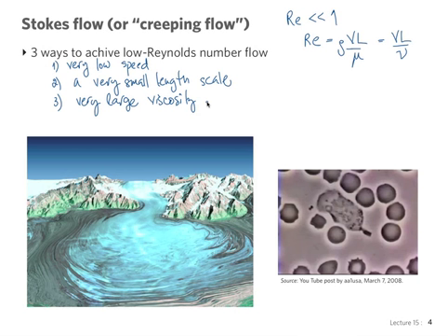So in the previous movie, we had a very viscous fluid with the little cherry thing floating, and the very large viscosity results in a very low Reynolds number, and we have a flow dominated by viscosity. Well, I don't know exactly what the Reynolds number might have been there. Perhaps it was larger than 1. It was a small Reynolds number, but perhaps it wasn't as small as what we use here to define creeping flow, which is Reynolds number much smaller than 1, so that viscous effects really dominate completely.